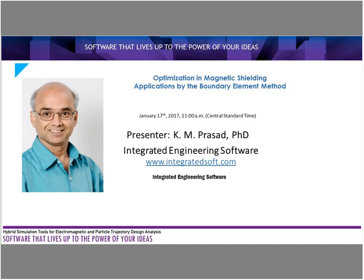Okay, can I check eddy current in the enclosure? Yeah, you can do that, but you have to use a different program, our program Faraday. What you are saying is that your shield has not only magnetic properties, it also has electrical conductivity. Yes, you can do that. The program needed is Faraday, but it will take more time also.